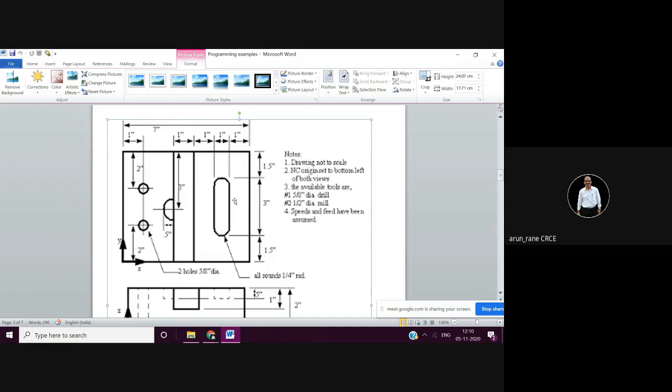Now this is solid, so I will have to go down slowly. So now I am going to use G01 and Z. How much is the depth? 0.5. But from here it will be 1.5. So G01 Z 1.5. Okay. Then that means initially I position the cutter here, then the cutter goes down. And then now I will move the cutter till here.